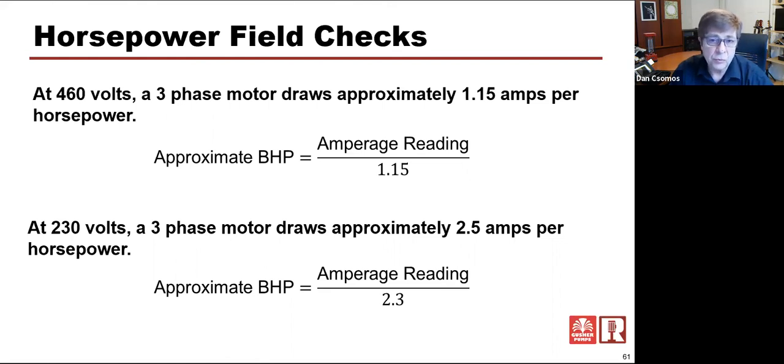And if that matches where you think you're at on the curve, based on the curve and the other calculation that we just did, then it's a cross-reference to be able to determine if you're operating where you think you should be. So it's another cross-reference back to the curve. And a lot of these things, when you go back to the curve, it can tell you how healthy that pump is. If you've got a lot of slippage, a lot of wear inside that pump, it's going to become less efficient. So your efficiency number changes, and therefore your amperage is going to go up for a given amount of work because your efficiency drops.